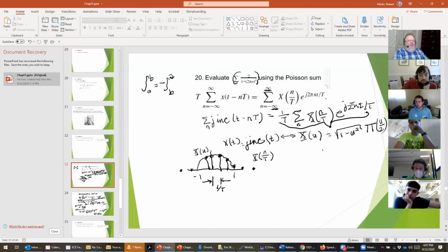You can do it two ways. You can look at the math and say, oh, this rectangle function prohibits me from sampling forever. But I like this geometric view, because this geometric view, kind of plotting out what the Fourier transform looks like, I think it's readily apparent just from the little sketch that I've done here that most of the samples are going to be 0. And I would suggest it works for me. I like drawing out pictures as much as I possibly can to help me visualize what's going on in these situations.